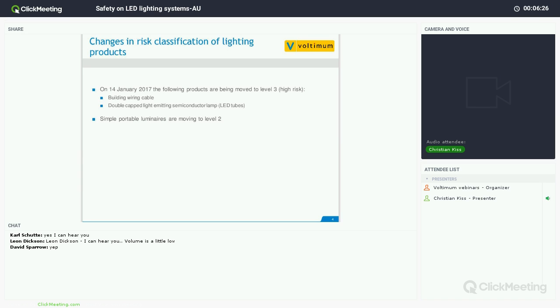The reason that that's relatively low risk is because certain components of that luminaire already have a level 3 high risk classification, as you'll see in the next slide. So, for example, the lamp holder needs certification, the cable or sheath cable, and anything that's got plugs, and even inline cord switches and so on need to have certification as well.